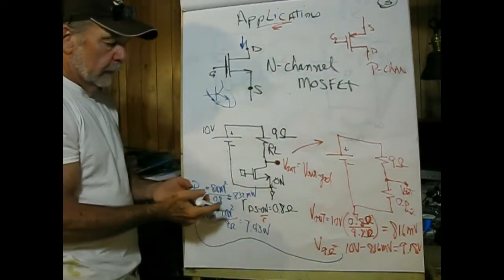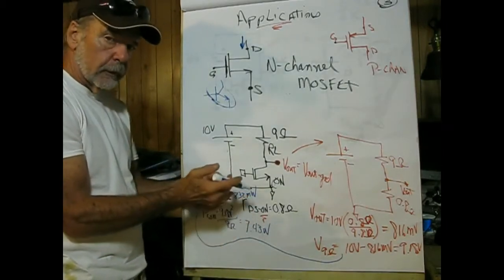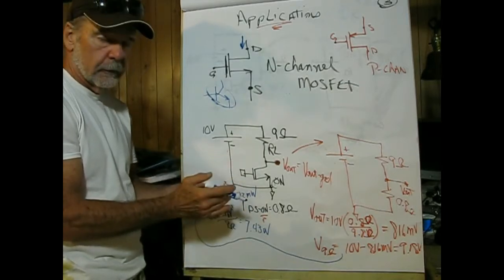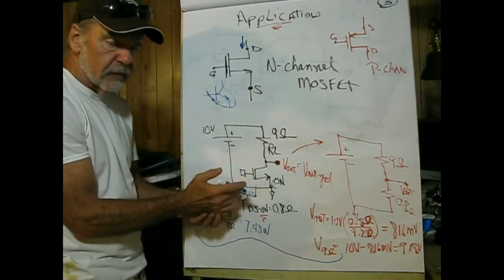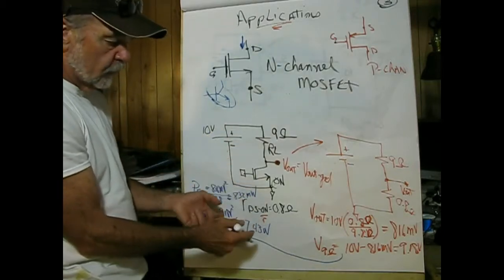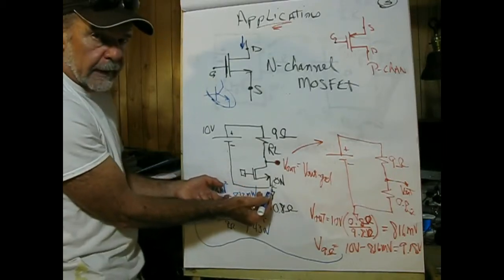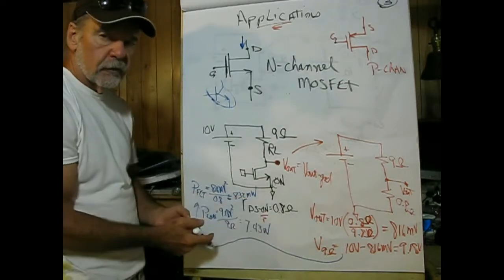If we go to analyze this, we're only interested in two states, completely on and completely off, because these are the most efficient. That is, the device dissipates the least amount of power. So we'll start by looking at this transistor when it's totally turned on, and it has this very nice characteristic that it looks like a resistor.